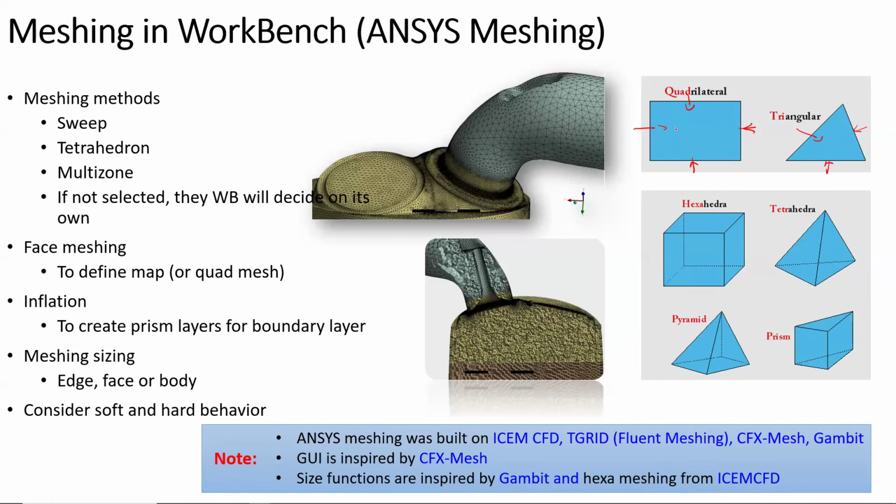One more thing is that if the flow is going in this direction, all the normals will be correctly predicted by the quad cell. But in the case of a triangular cell, the flow is going in this way, so its normal is going to be here, but the actual face shape is inclined. Then we have to apply different interpolation schemes to get data on this surface here. This will definitely introduce some errors. Now imagine that we have thousands, or maybe 1 million, or 1 lakh of these faces which are not normal to the flow direction.